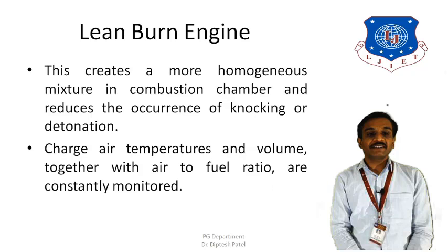The mixture is more homogeneous inside the combustion chamber because we use a proper amount of swirl, with special swirl control valves, to mix the air fuel mixture before it enters the combustion chamber, and therefore the tendency of knocking and detonation is reduced.